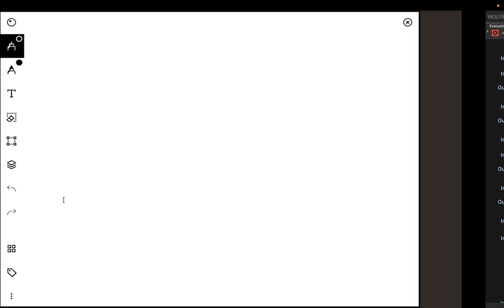Now, for the horizontal case, we have to consider the two surfaces separately, because the top surface will have a higher heat transfer coefficient compared to the bottom surface. As we discussed before, when you have a hot surface at the bottom, the flow will be restricted. When we have a horizontal surface like this, the flow will be restricted by the plate itself, and because of that, your heat transfer coefficient will be lower.